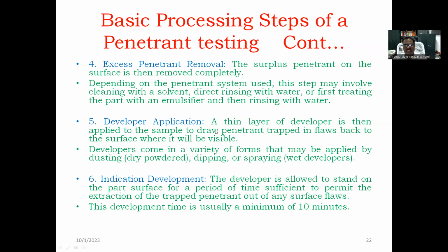Developer application: a thin layer of developer is then applied to the sample to draw penetrant trapped in the flaws back to the surface where it will be visible. Developers come in a variety of forms that may be applied by dusting dry powder, dipping, or spraying wet developers.